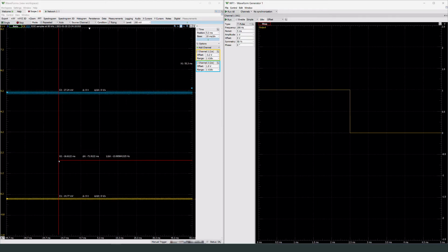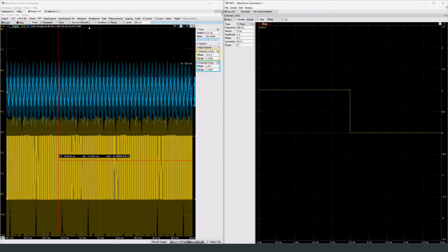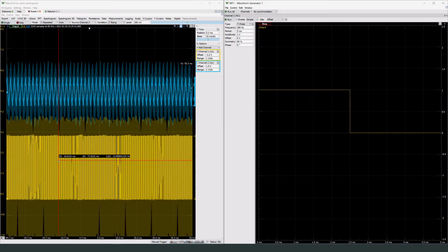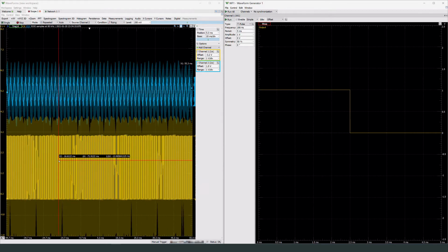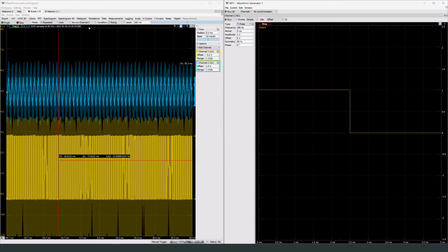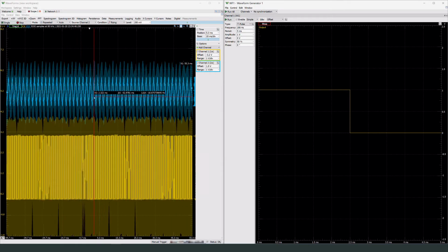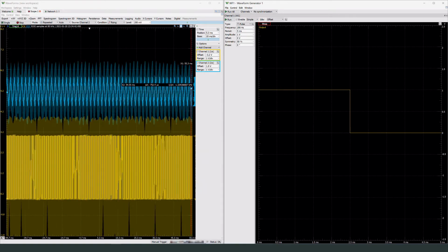I'm going to plug the Arduino in so we can start using that as the output to show you what some of those signals look like if we have more resolution in here. So this one right here is, I believe, 8 points of resolution per wave, and I think it's doing a 500 hertz signal. But we can check that out.